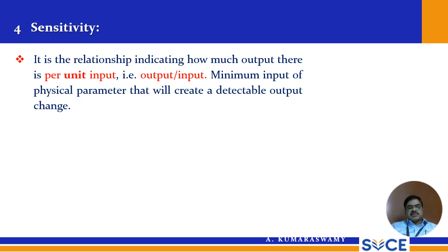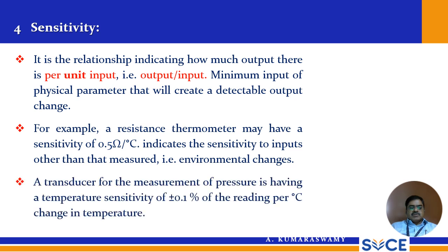Sensitivity is the relationship indicating how much output there is per unit input. So the output-by-input relation is known as sensitivity. It is the minimum input of a physical parameter that will create a detectable output change.